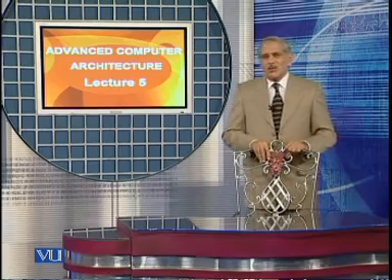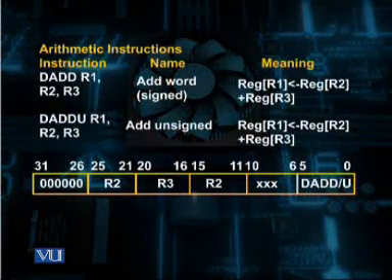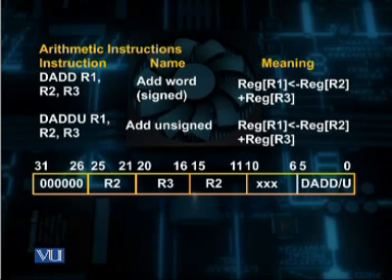Whereas in the machine code or in the instruction word format, moving again from left to right, first the RS and RT, that is the two source operand locations, are defined, and the third register over here is the destination register. So these two sequences are opposite to each other.